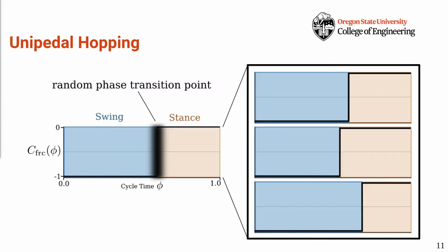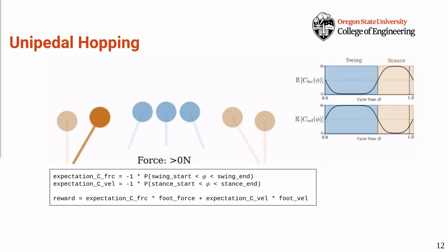We use a probabilistic model of the transition timing by making the transition point between phases a random variable. Now, our transitions are subject to some randomization, and we've captured the uncertainty about transition timing that our step function couldn't. This yields an explicit distribution around the time of transition between each phase, and we can modify its positional mean and variance. Since we parameterize the phase transition point with a probability distribution, we can calculate a probability that the swing or stance phases are active given the phase time phi.